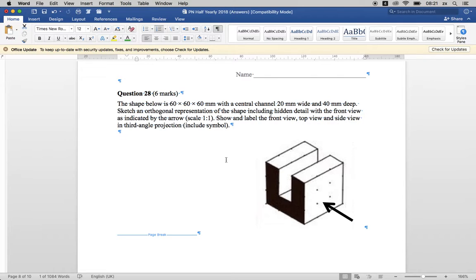Most people were able to show a difference between their dark and light lines, and most people drew a solid line using a ruler, and that's fine. Some people did freehand, and it was a single straight line, or a single attempt done with determination, is what I like to think of. What I don't like to see is feathered lines, and if someone has done feathered lines, I'll usually say don't do this, and I'll indicate what a feathered line is and the difference between the two lines.